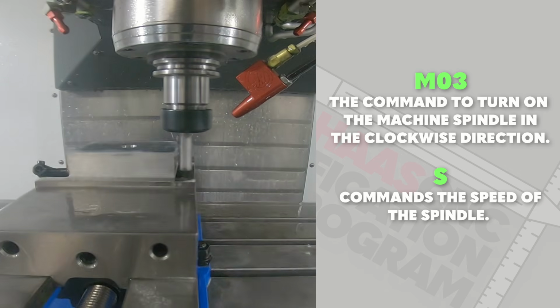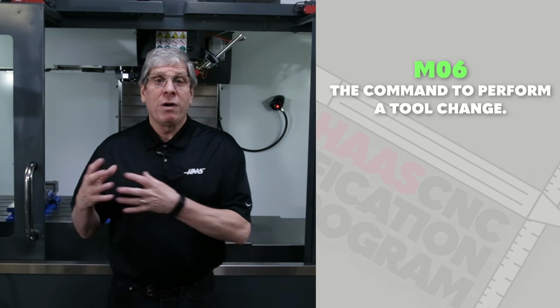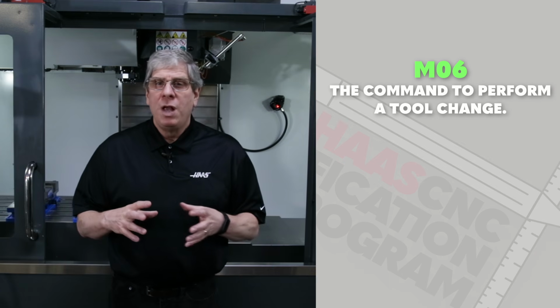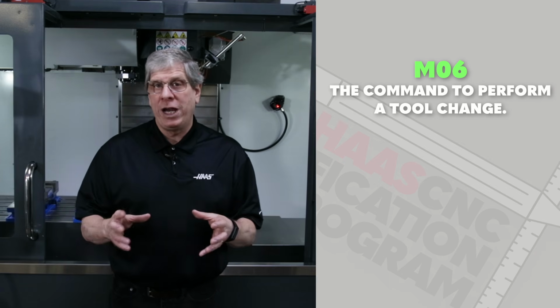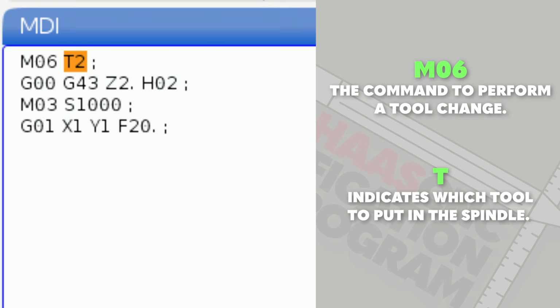Another M code example is M06, which is the command to perform a tool change. So if we enter M06 on its own, we're asking the machine to change tools, but we haven't told it what tool to change. The letter address T indicates which tool to put in the spindle. So we add T2 after the M06 command.